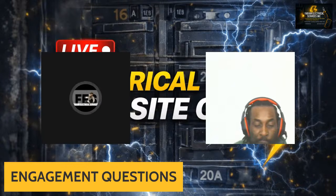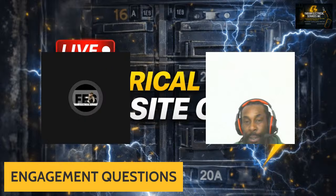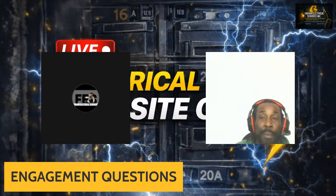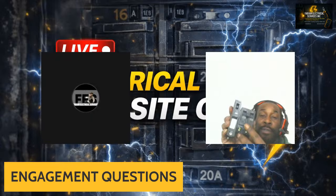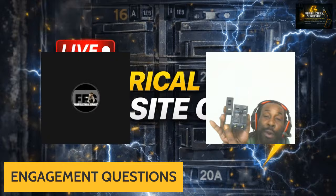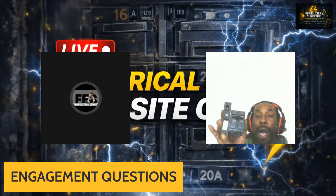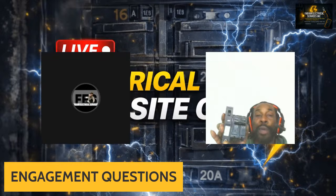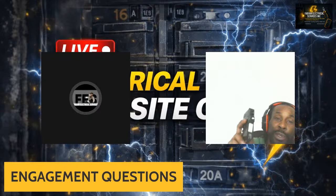Again, what these breakers do is size your cable accordingly. You cannot use a 14-2 wire on this breaker here. You can only use it on this breaker. Why? Because the breaker does not protect the wire itself.